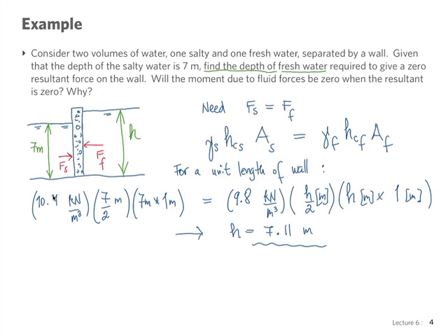The point of action is the center of pressure, and in shortcut number 2, we know how to find the distance between the centroid and the center of pressure, so we can find the point of action of the resultant force for both cases. So let's look at the moments now.